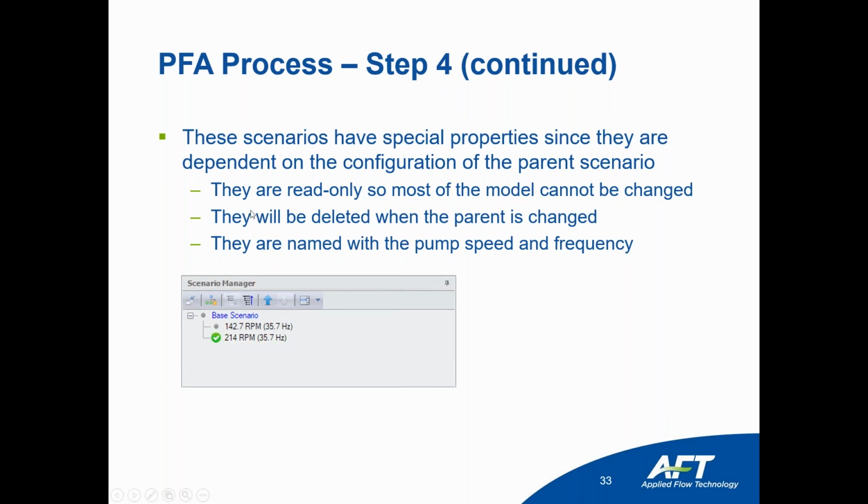The peak-to-peak pressure occurred in pipe 8, station 1. The maximum allowable for the API is 188 psi. Vapor pressure margins are within the allowable levels.